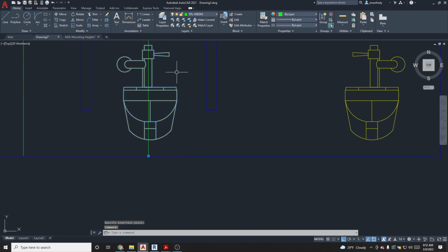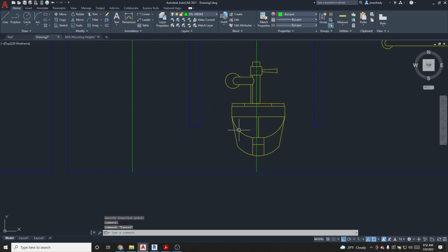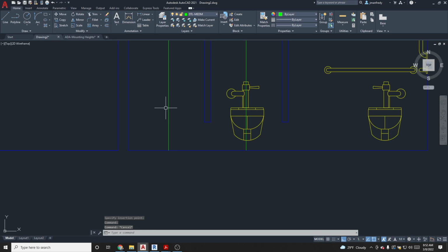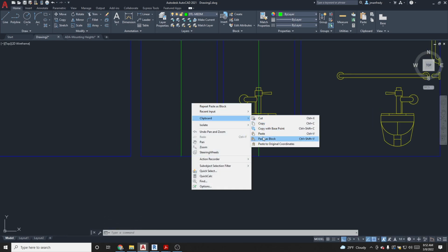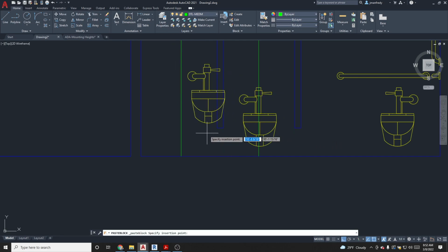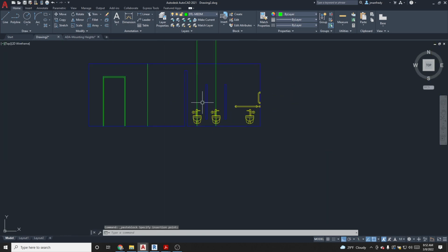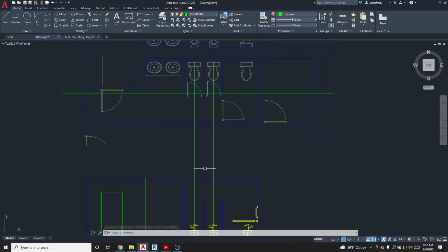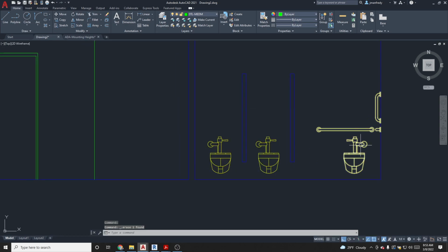So that is a block. I want to insert it as a block, so don't forget that step. I previously forgot that. Now, this block has been copied. This block is exactly the same. I know exactly where it goes right there on the floor. I can right click, clipboard, paste as a block again, and place it right there. And so these guidelines help me determine where exactly to place those laboratories here. And these can be deleted now. So now I've got 3 labs here with the hardware located here on the wall for handicap accessibility.